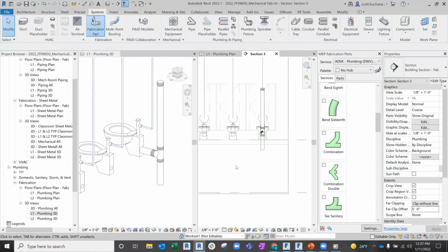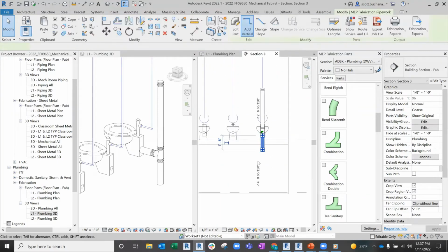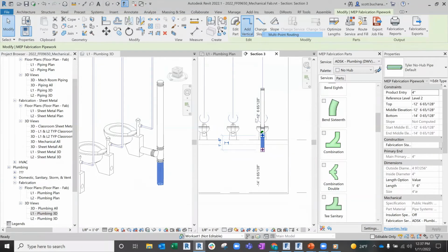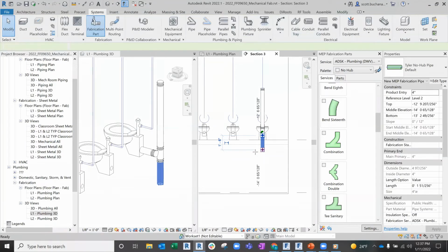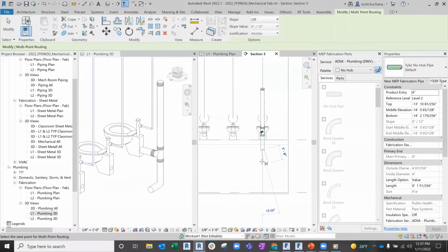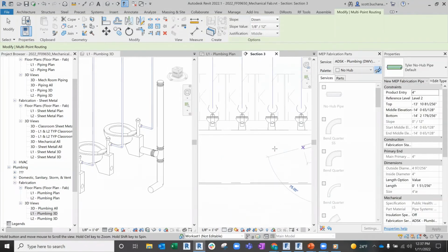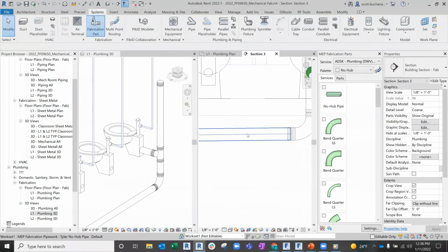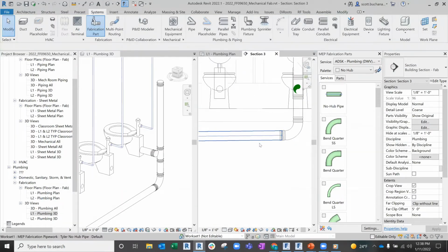Right, so then I could have just routed straight off of that thing from there the exact same way. Now with this, we've got the ability to turn on that slope, right? Or maybe I needed to drop down a little bit more. If I turn the slope on, we're going to slope down, go 1/8 inch. And again, you can do something simple here, run that out, and you can see from the bent lines there, there's our slope added to it.